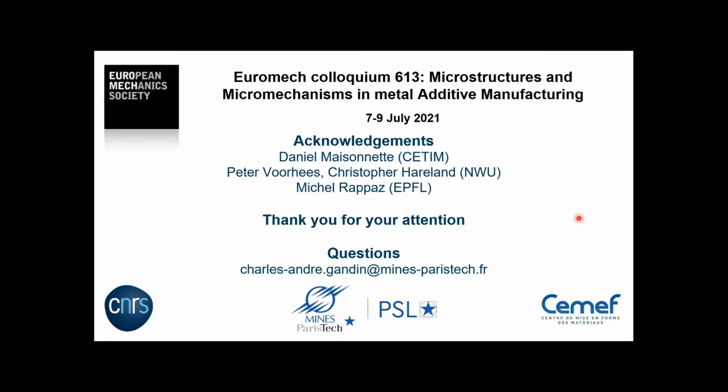Well, I would have needed half an hour to explain this model in detail. Okay, we don't have half an hour. So that was a short one. No, but so we have an equivalent medium, and of course one of the main things is the thermal conductivity of the powder. So we have a model that, as a function of porosity and size of the powder, gives you the equivalent thermal conductivity.